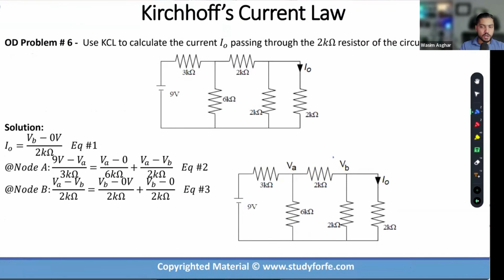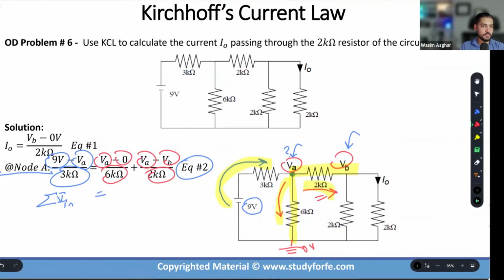They're like, okay, you know what? Now I feel like the direction of this current is towards the left and this one to the top as well. Please don't do this. That's where your assumptions have to make sense with the equations. Once you have assumed the directions, they're frozen for this circuit analysis. You cannot just go back and forth.